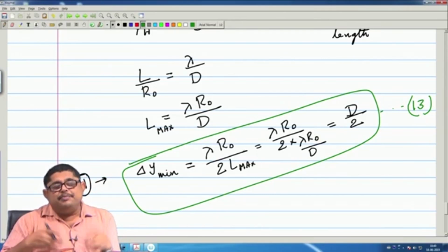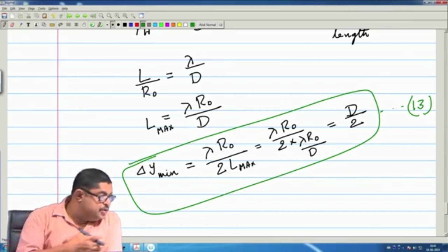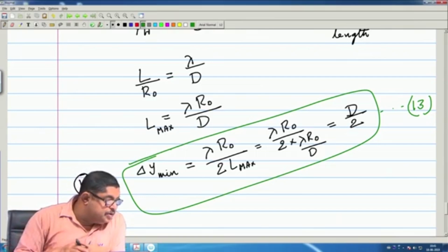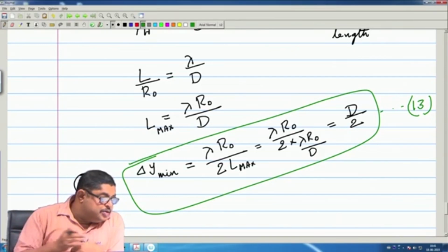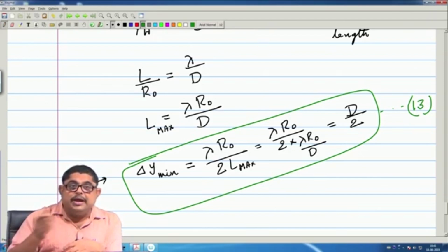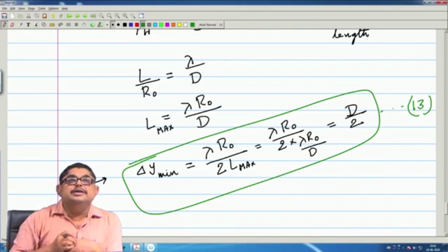So, received signal strength will decrease if the gain is less, because it is a two-way gain for radar, since it is sending and again receiving.